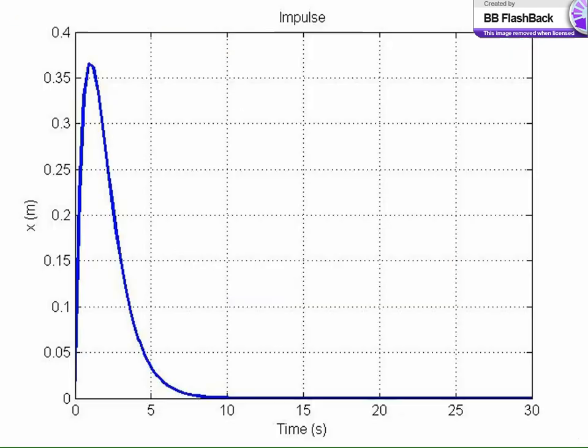And that response is actually identical to what you would expect for a first order system, or something with just one derivative. Not identical, but very similar. So we have our initial push. The response goes up, and then it follows, and it is bounded by that exponentially decaying term.